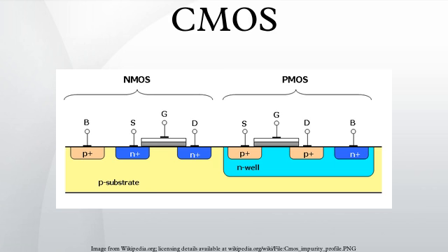To speed up designs, manufacturers have switched to constructions that have lower voltage thresholds, but because of this a modern NMOS transistor with a VTH of 200 mV has a significant subthreshold leakage current. Designs which include vast numbers of circuits which are not actively switching still consume power because of this leakage current. Leakage power is a significant portion of the total power consumed by such designs.